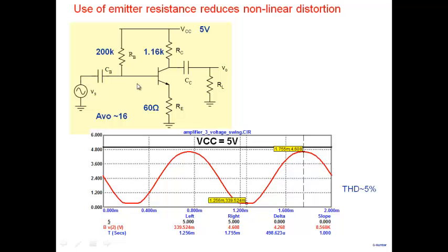All right, so this stage sort of specializes in getting you a good swing. It gives you a gain as well. It's not that there's no gain. And in fact, if you're bothered about 5%, I could have reduced the gain even further from 16 to maybe 3 or 4 and obtained more linearity, even lesser distortion. So you sacrifice gain here and build the gain in the previous stage. And in this stage, you try to get a good swing with low distortion.